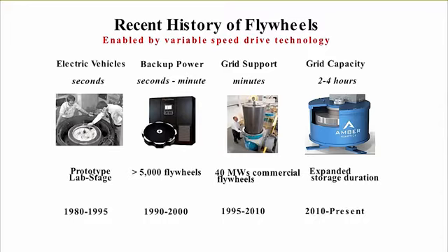And so it's relatively challenging to have a system that is highly efficient in terms of rotating losses and so on. But with a so-called modern example, one has a sealed box with some relative vacuum inside the sealed box, and then the energy is imparted and taken out with an electrical machine that operates in that low pressure environment. And it's driven by the technology that enables variable speed drives, so that's power electronics. In some sense, this is the enabler for the modern era of flywheel energy storage.